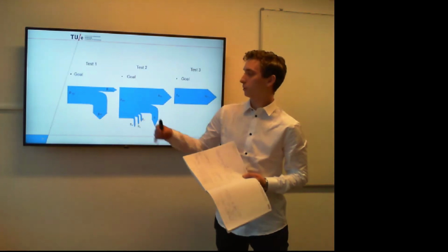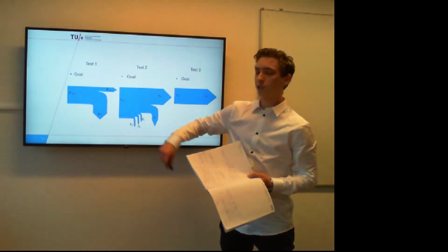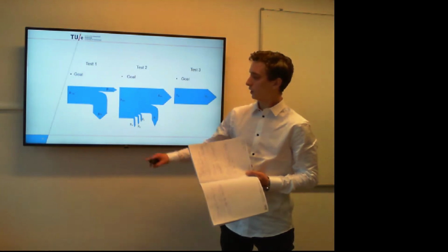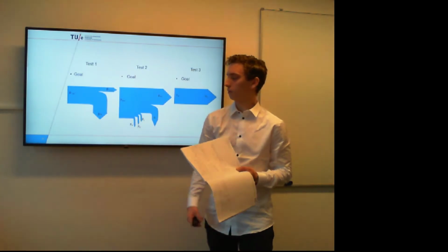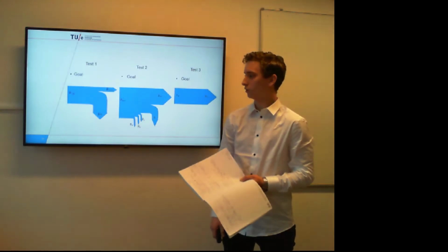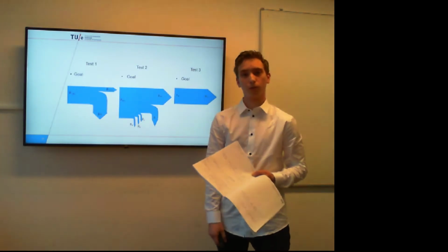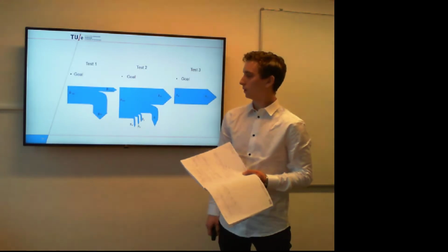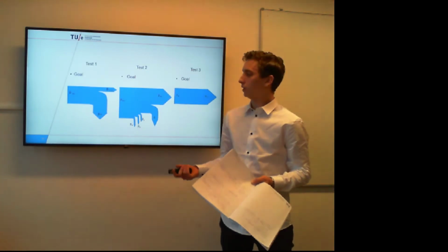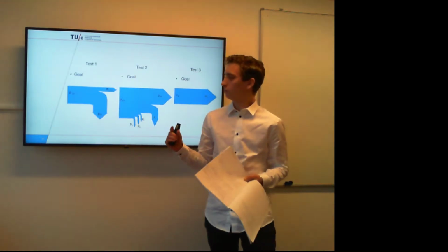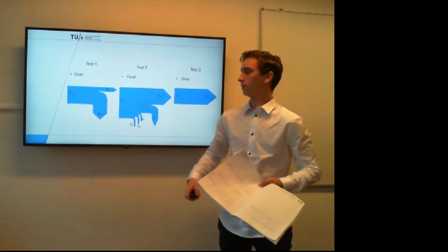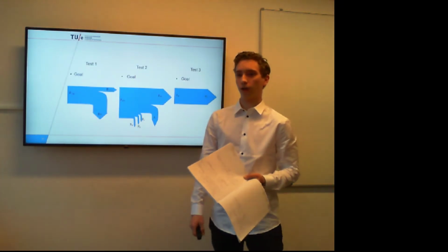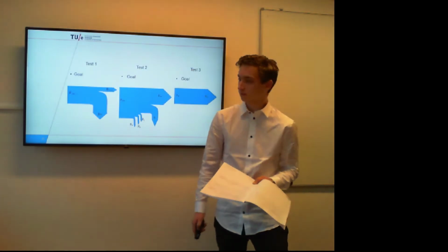So P-rotor is like P in, P-friction is the friction of the gears, and P-r is the power loss due to traction tire force. In test 1, we will skip the P-friction because that value is going to be really low, so we can almost neglect it. And this will help us to calculate the tire resistance on the roller.